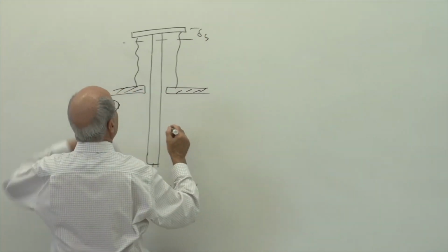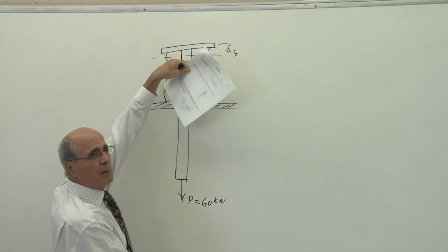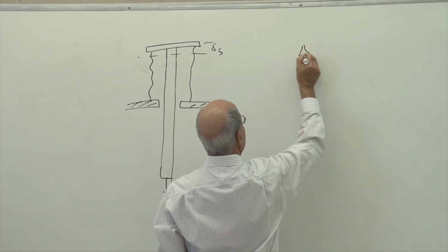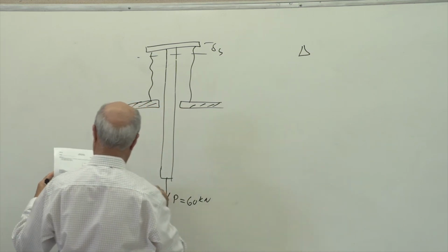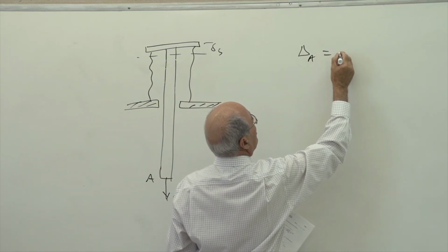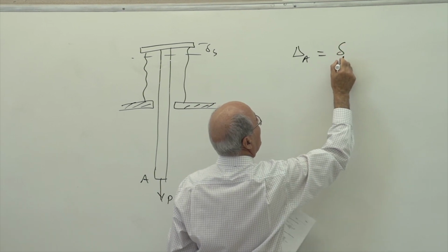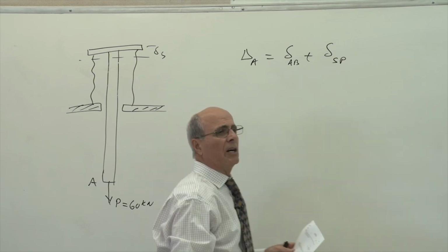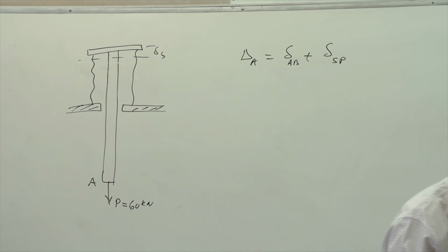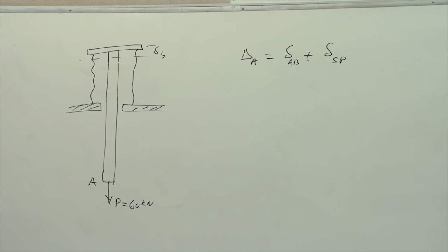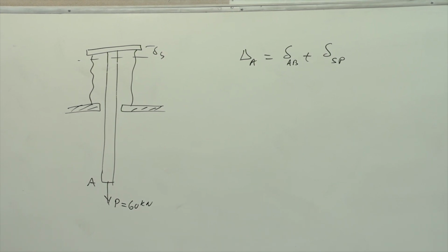But at the same time, when it comes here, the rod is already being stretched downward there. So I need the displacement of point A of this system is actually equal to delta of the rod AB plus delta of spring. Is that understood? Because both of them moving in the same direction. Notice the first example, they were against each other. I have to subtract. Here, both of them moving in the same downward motion, correct?